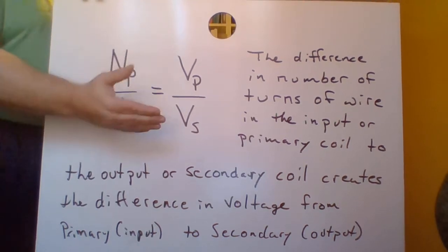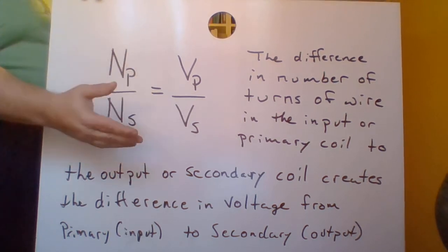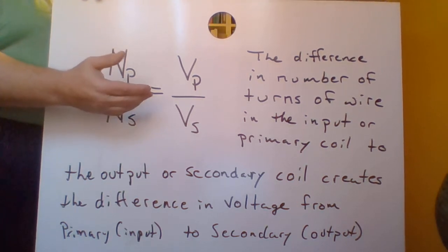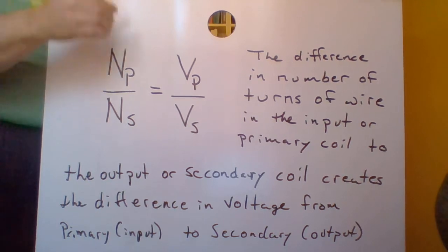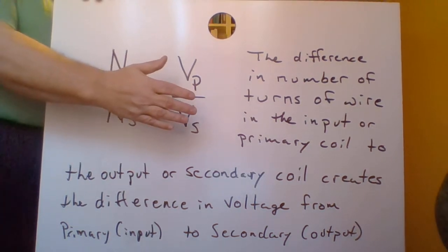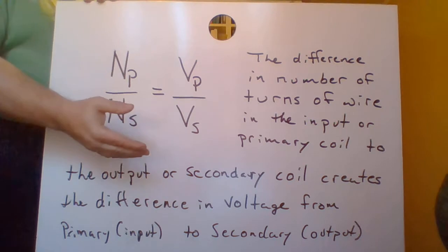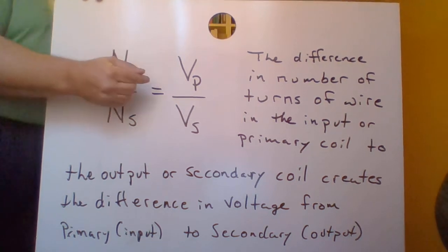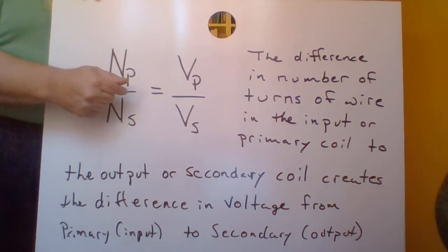All right, so 2,000 volts times, let's say 100 amps, and we've got 200,000 watts of power that's being produced by that generator. But if we try and push that out through wires, it's going to cause the wires to heat up. It's going to cause the wires to melt. There's going to be a huge energy loss going through the wires. So Tesla proposed that, hey, we put that AC power on a transformer and we boost that 2,000 volts by 1,000 times, make it 2 million volts.